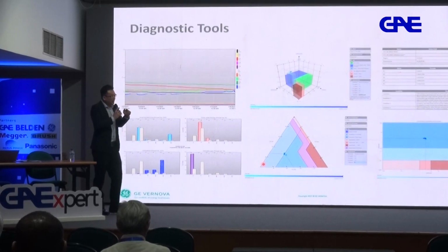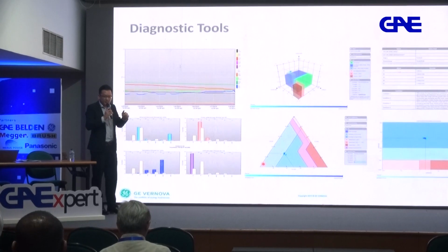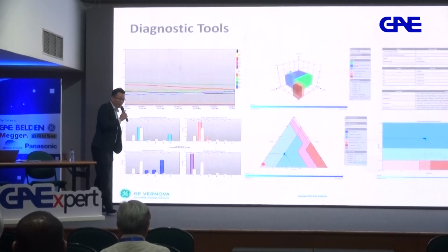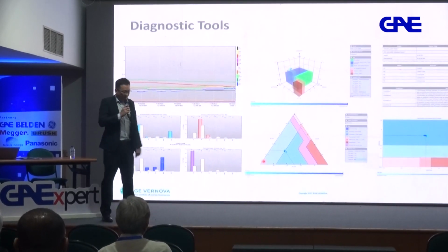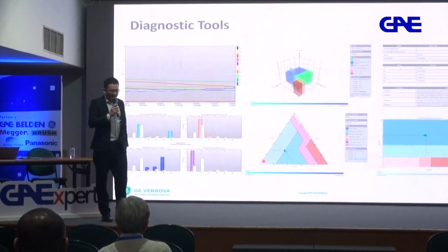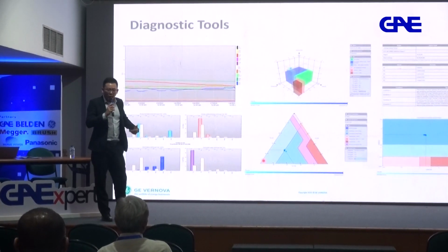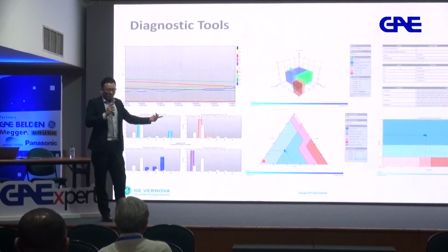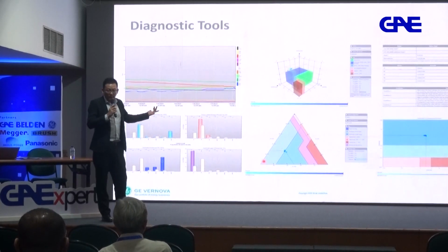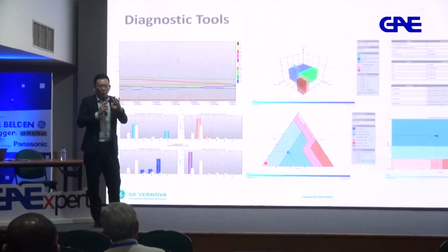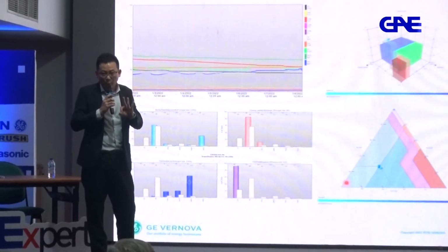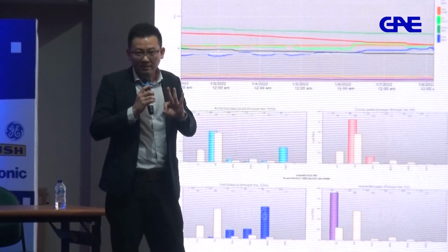But of course, in the event that I realize my hot metal gases rise up, then I want to identify in a very short period of time what exactly the fault is, in order for me to take another action. For GE Online DGA, you can actually set 30 minutes for hot metal gases only. Hot metal gases, so 30 minutes.